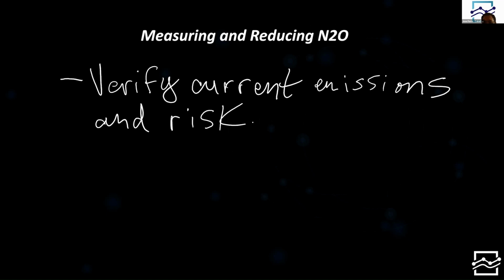So first, we want to be verifying what the current emissions are, because at this point, we've been using our machine learning model library, which can give us very good results and fairly accurate numbers. But those are models, and even though we have over 50 models in the library with varying process conditions that can be matched to your process conditions, they're still not going to be perfect. There's no perfect model out there. So it is always going to be good to verify what the actual emissions are with physical measurements.